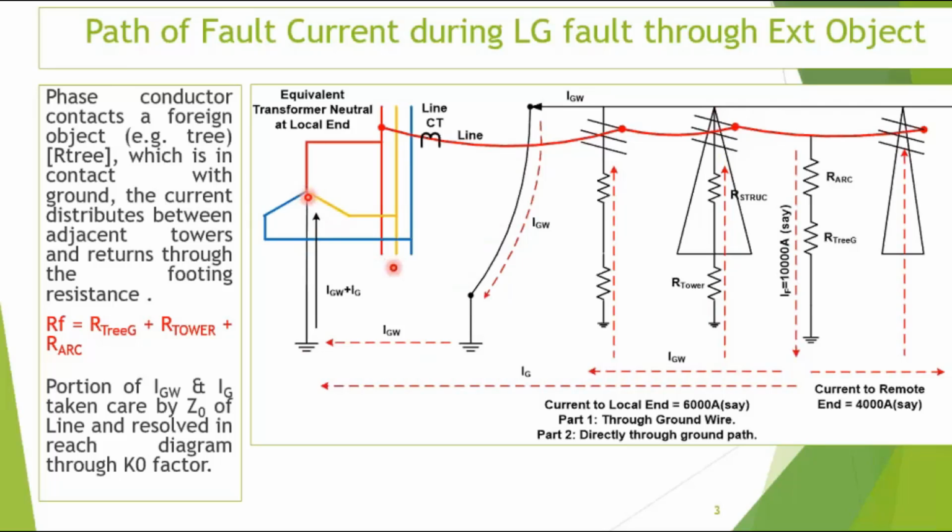Now, this substation does not mean only the nearest substation. It can mean various other substations too. From the other substations, the current will get summed up via various lines and come to this particular R phase via the other lines, which I have not shown over here. It was not possible to draw everything over here. So Ig represents all those currents which are going to other substations maybe.